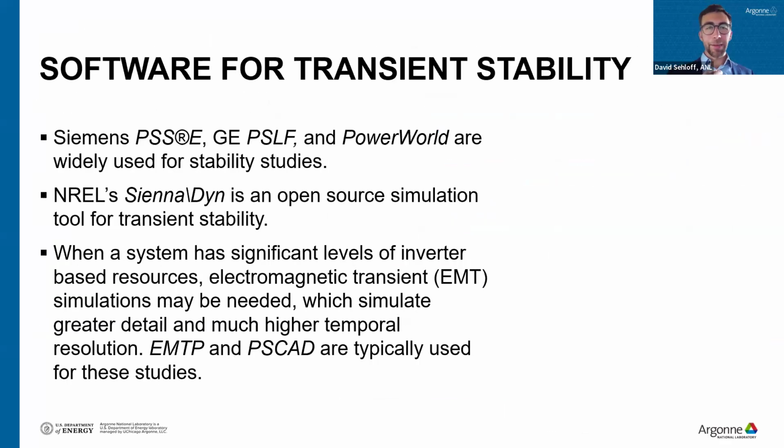So a lot of the same softwares like PSSE and PSLF are used for stability studies. There are also open source tools that can do that. Electromagnetic transient studies where we're looking at really detailed switching dynamics can be required when you have a lot of inverter-based resources.